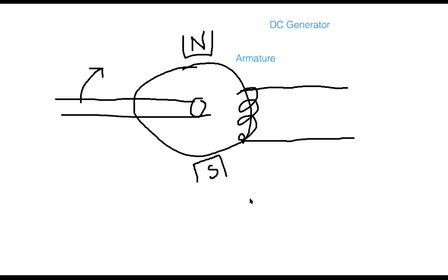You see, this is just opposite to the synchronous generator. In the case of a synchronous generator, we learned that the magnetic field rotates with the help of the shaft, and the armature remains static because the armature has three-phase coils and during movement those coils might be deformed or shorted.